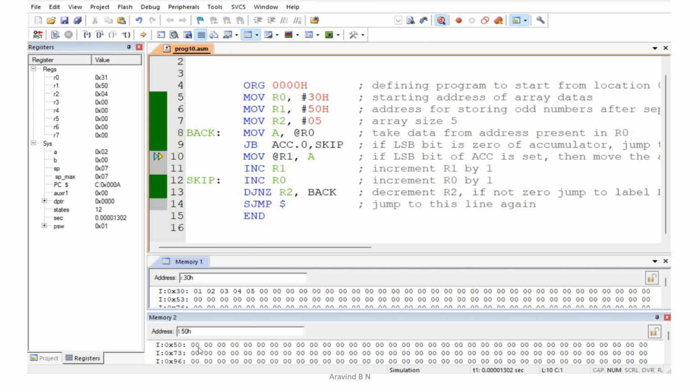That instruction is the memory location starting from 50H. That is at this memory, as you can observe, all values are now 0. Now the value from the accumulator will be stored to that location. So now as you can observe, the 2 has been stored in the memory, that is the starting memory location 50H.